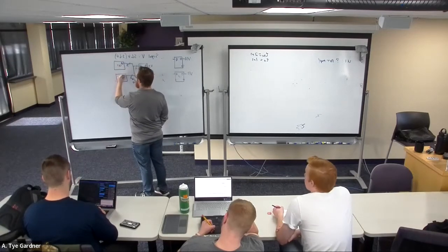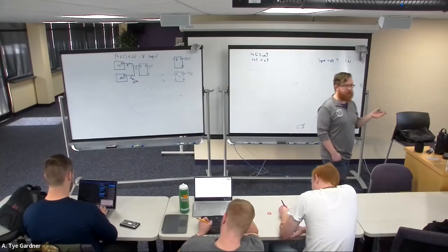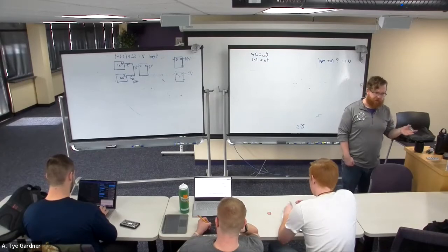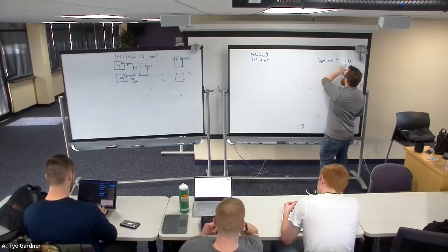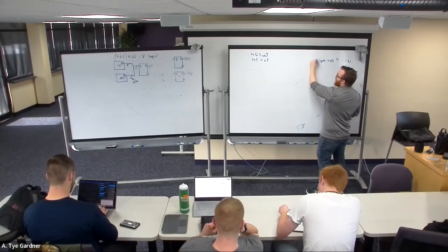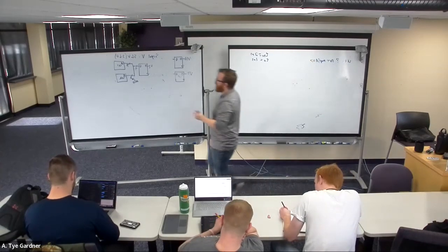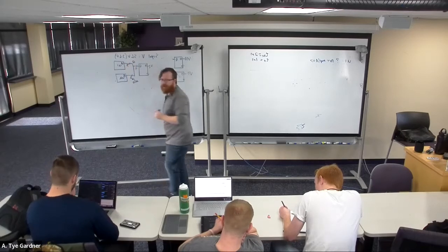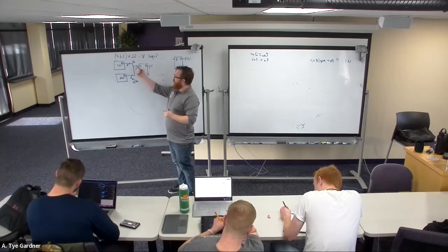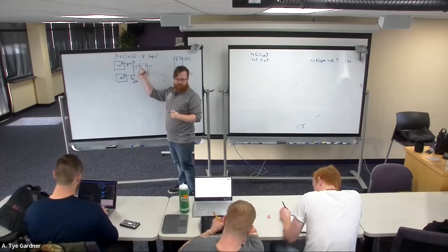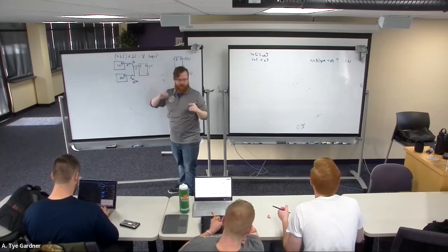A, B. Those could both be port A's, right? Nothing stops me from having the same port names as long as they're not inside the device. Then this would say, well, this is U1, which I've drawn over there. I would say A gets mapped to, if I call the signal Q, which is allowed, right? So V is the input to D, Q is the signal output of port Q. This is fine. It's okay to have different names or same names between the port and the signal that plugs into it. Either way is okay.